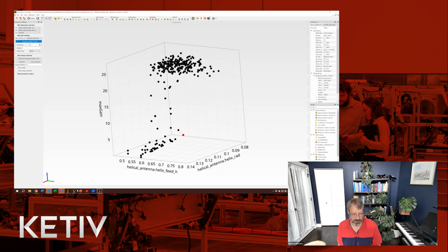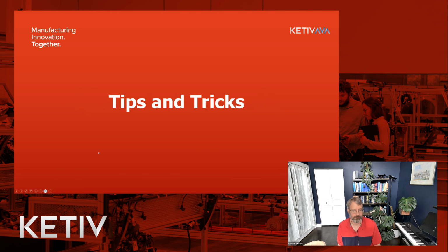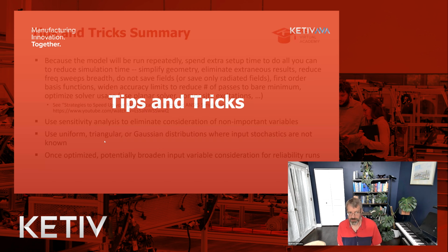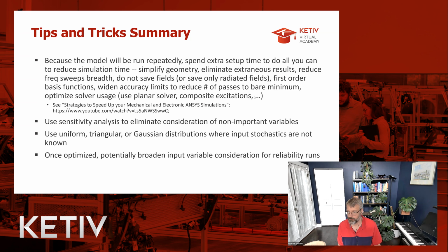So that's the results that I wanted to show you here. And if we go back to the presentation along tips and tricks, I just wanted to remind you of a few things. Because the model will be running repeatedly, 500 times, 1,000 times for Monte Carlo analysis, this is the time where it is worth spending a lot of extra setup time to do everything you can to reduce the simulation time.